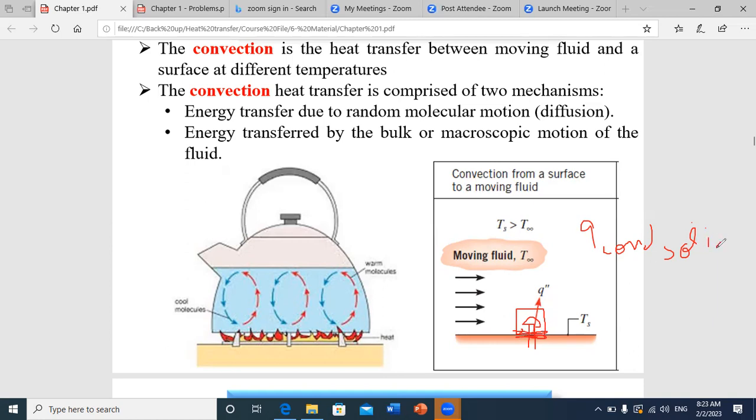This conduction flux that is coming from the solid through air at y equals 0 will be convected because of the fluid motion. Imagine that your fluid is moving, then you will have a flux entering this face at a certain energy, and here you will have a flux exiting the face. But because you are receiving a flux, what will happen to the energy of the convected flux at the outlet? If you compare the convective flux at inlet and convected flux at outlet, which one will be larger?